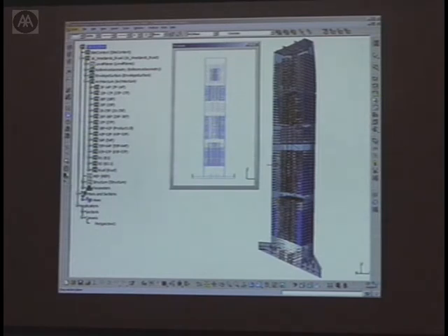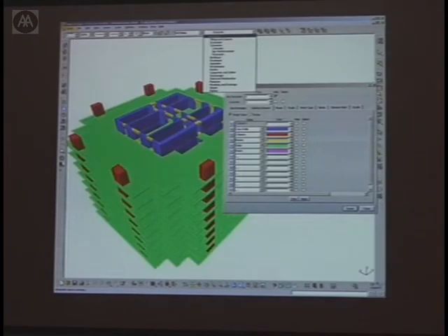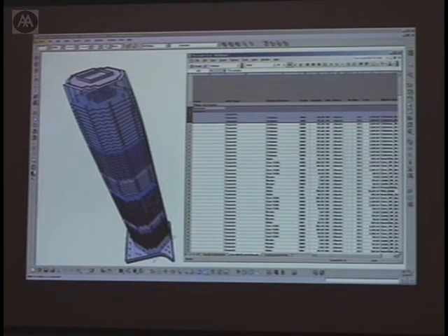You can do lots of other things, obviously, out of that model. You can produce drawings, you can analyze it, query it in terms of producing logical representations of the building. Show me all the structural shear walls that are of a particular type of concrete mix. But also the idea that when you do a sort of financial analysis or material quantity analysis of the building, you're actually getting what is basically a different kind of view onto the same project.